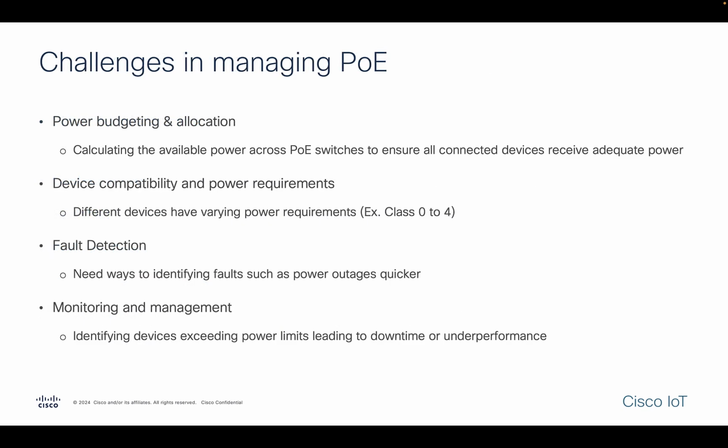Though PoE offers a lot of benefits, it's not free from challenges. One of the fundamental challenges in PoE is power budgeting. PoE switches have limited amount of power they can supply to its connected devices. And also, different devices use different power levels, so the calculation becomes really important. Next comes the device compatibility. Understanding the device compatibility is essential to make sure the PoE switch can deliver the necessary power without exceeding its limits.